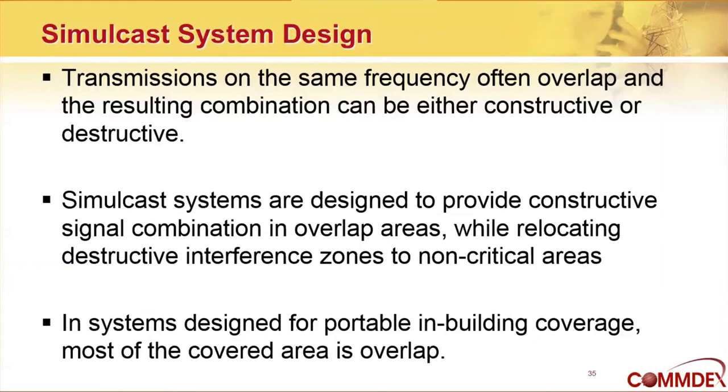So a system is designed to provide constructive combination in the overlap zones. In the non-overlap areas, if you are close to one of the transmit sites, you're in the site's capture area and you'll be fine. If you're in an overlap area, you want to be able to receive the signal simultaneously, in phase, from multiple sites. So that's where the design comes in.